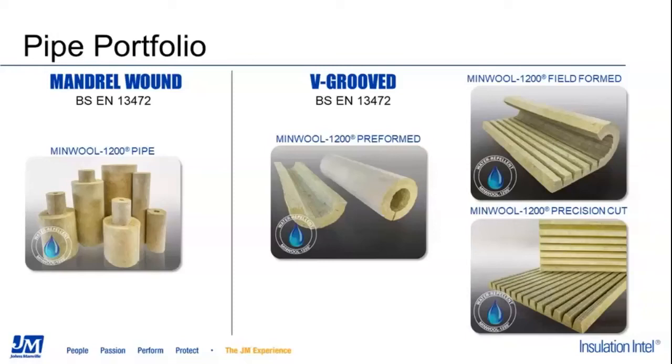There is an adhesive sprayed on the walls of the groove so that when you wrap this around the pipe, it does hold its shape similar to the shape of the molded or mandrel wound product. There's also a pre-formed version that's offered where we actually take those V-groove pieces and pre-shape them into the round format for you instead of shipping them flat. And then there's the precision cut version, which is the same as the field form version, only there is no adhesive in the grooves.